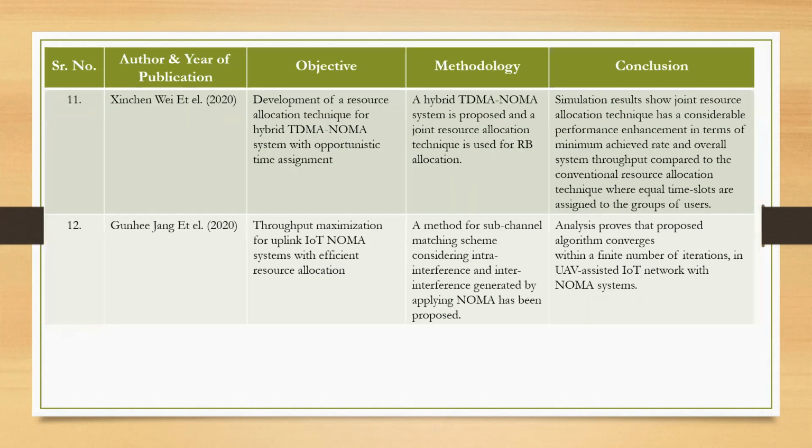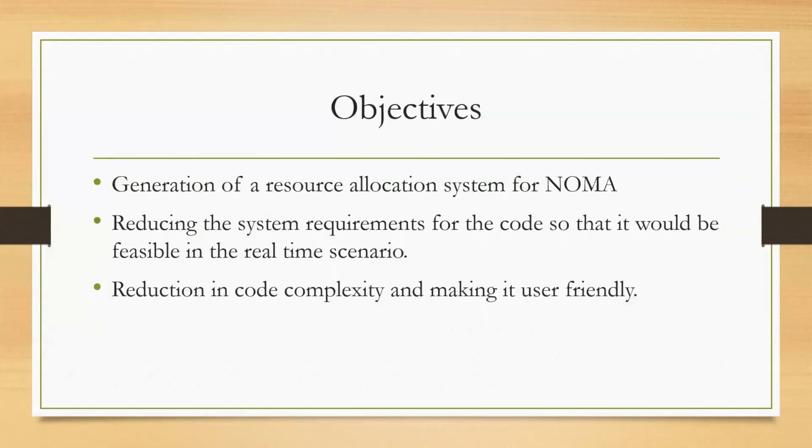So there was a requirement in this NOMA system to use a particular algorithm which doesn't affect much of the spectral efficiency, but reduces the energy requirement of the system, as well as it doesn't affect much of the time complexity. It basically reduces the time complexity or whole complexity of the algorithm.